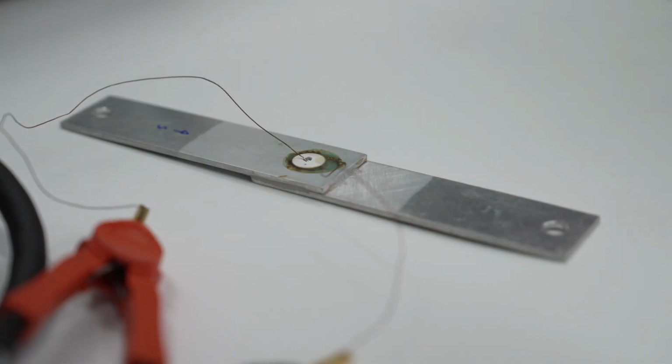In electromechanical impedance spectroscopy, or EMIS, we make use of an impedance analyzer here and of a piezoelectric element here that is bonded to a specimen or structure under evaluation. In this method, we excite the piezoelectric element with an electrical signal of various frequencies, and for each frequency, said signal will generate a mechanical vibration on the structure.